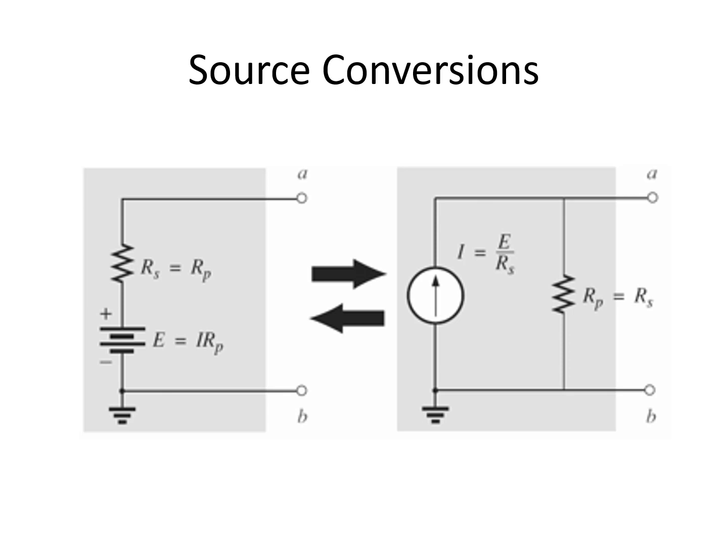So that means when you have a voltage source, you can convert it into a current source. How do you do that? We have here the voltage divided by the resistance, and that is the equivalent current source. And then your R_S here in series is just equal to your resistance here in parallel, so they are just equal.